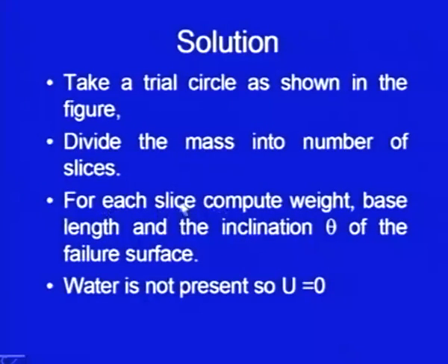So, for each slice compute the weight, also compute the base length and the inclination theta of the failure surface. In the present case water is not there, so u is equal to 0, otherwise there will be some u value. We have already discussed how to find out the u value if seepage is there, and you can calculate it from the flow net, etc.